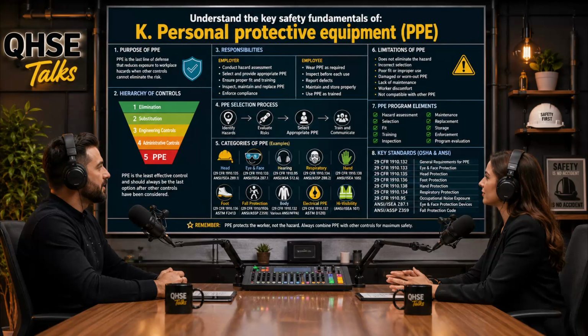This is the absolute maximum legal concentration of a specific chemical or substance a worker can be exposed to over an 8-hour shift. Exactly. And the final variable is what we're usually trying to solve for, the MUC, or maximum use concentration. This is the absolute ceiling, right? It is the highest atmospheric concentration of a hazard where a specific respirator can still mathematically keep the worker's internal exposure below the legal PEL.